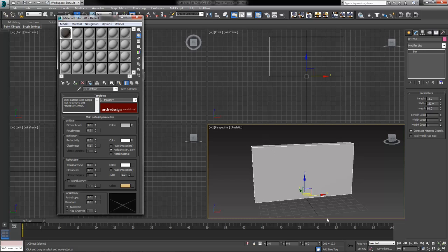You won't be able to see these bricks on our brick wall until we've done one more thing, beat it into the ground until we remember it completely, right? And that is toggle on the Show Shaded Material in Viewport button right there. Fourth one in from the right side underneath our sample slots in the material editor. From here, we're going to use this as our standard. We can now see our bricks on our wall here, which is all we need to worry about right now.